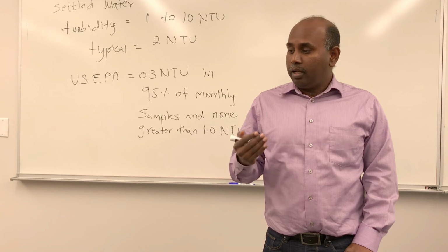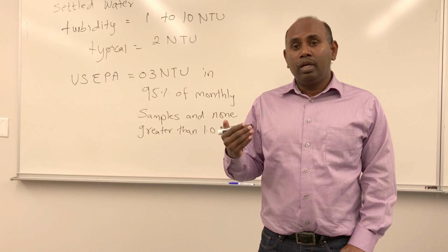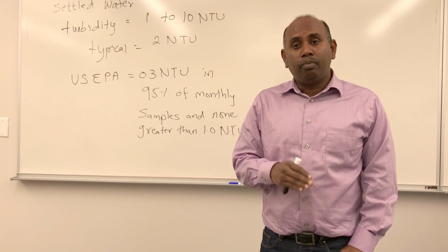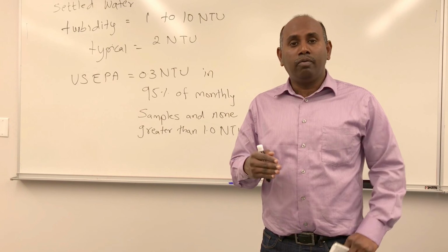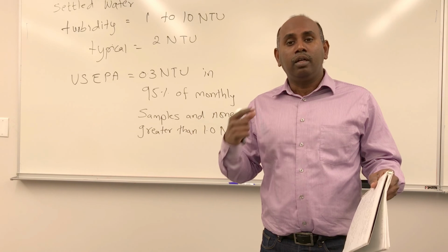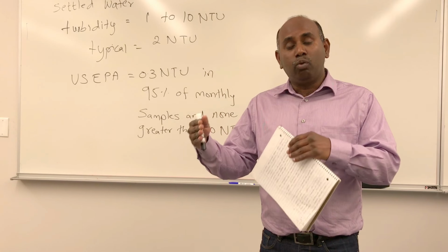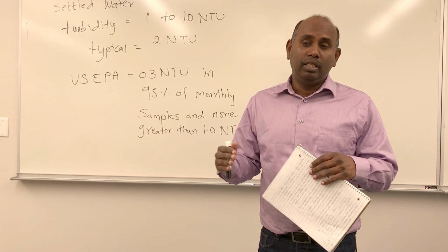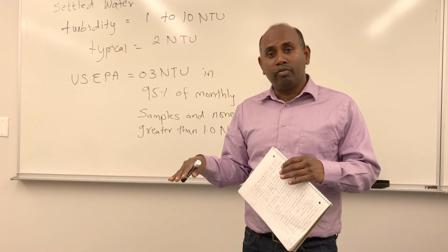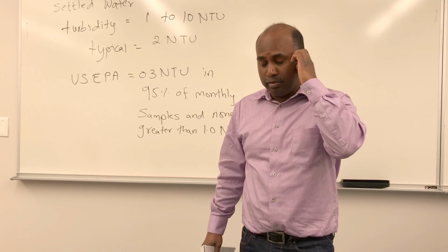So we looked at adding alum, the effect of alkalinity and pH on alum working as a coagulant. We looked at the same for ferric chloride, and after coagulation, we worked on the flocculation basin. We designed a flocculation basin, looked at how the flocs are formed and why flocs should stay in water, not settle out in the flocculation basin. And then we designed a settling tank where the flocs were allowed to settle to the bottom of the reactor, and then the clear supernatant flows out of the settling tank or sedimentation basin.